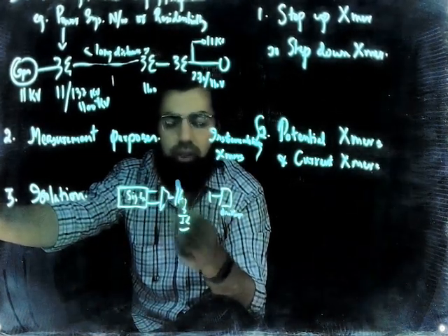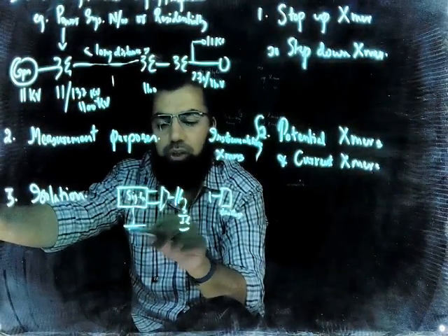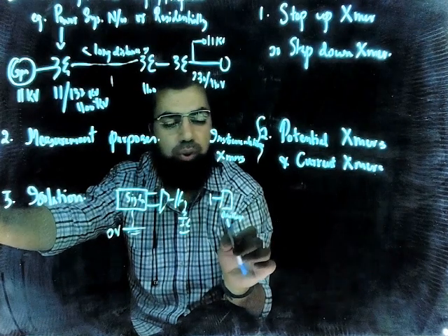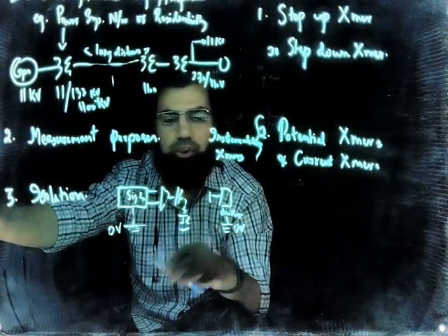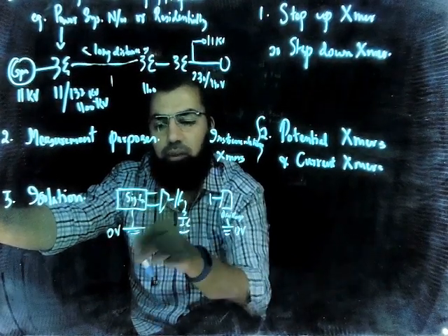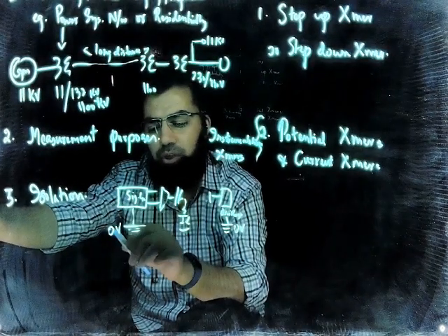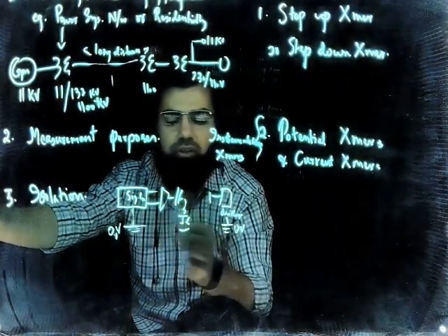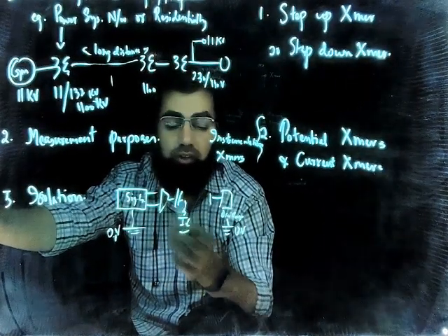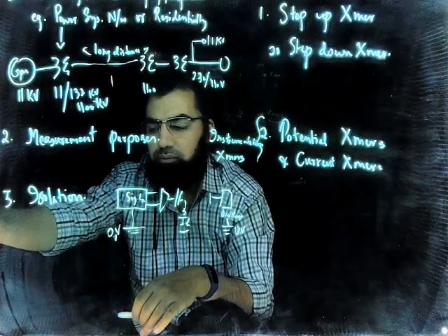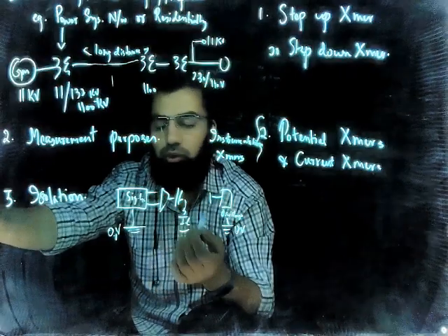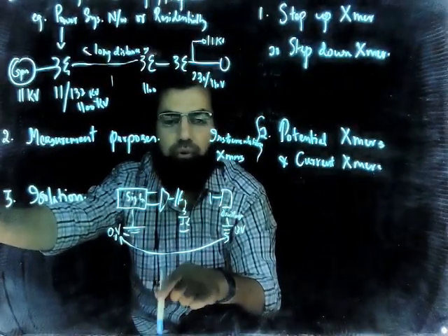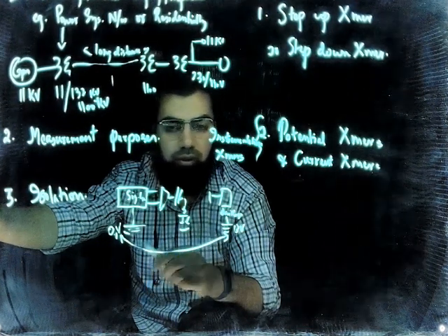So in electronic circuits what happens is that the ground potential, we assume, we hope that it is 0 volts, but the ground potential will not always be 0 volts. Say for example for this circuitry the ground potential is 0.1 volts and the ground potential here is 0 volts. So the potential difference between these two circuits is 0.1 volts. And if the resistance is say in milliohms, you can understand what will be the value of current that will be created because of the potential difference between the grounds of two circuits. So this should not happen.